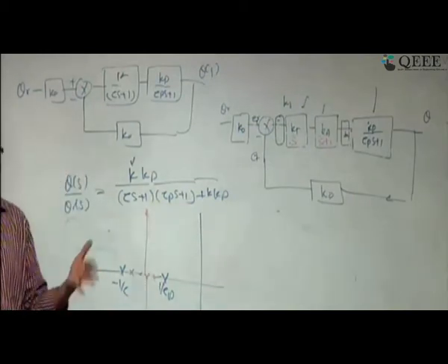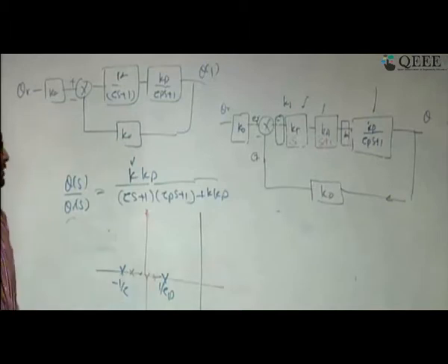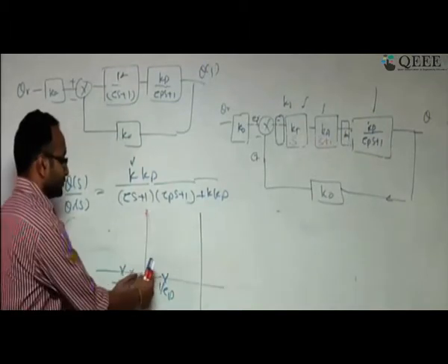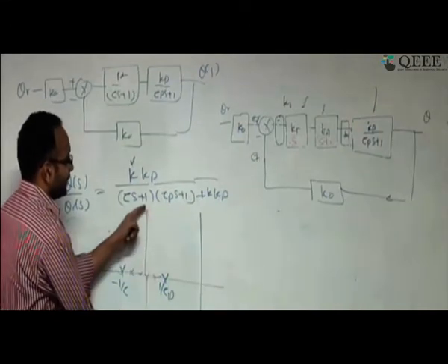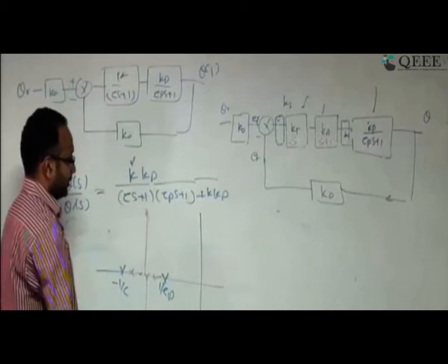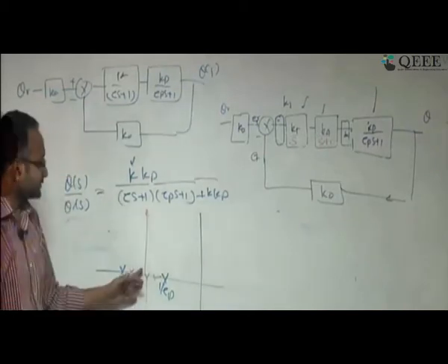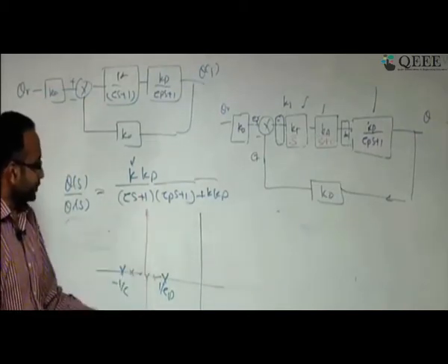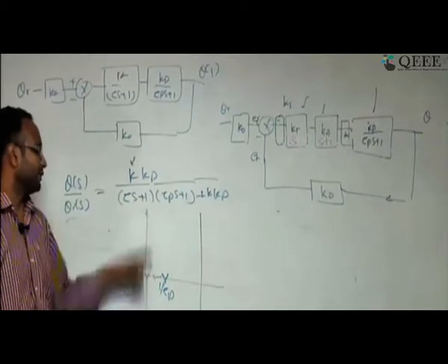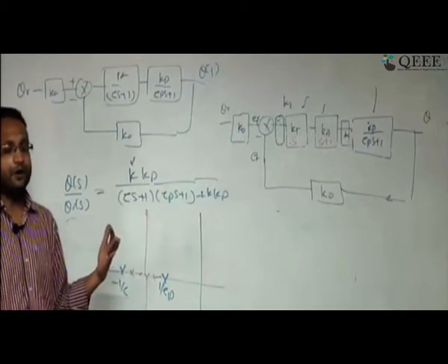You can check it by using different values of k. What happened? K equal to 0, 0.1, 2, 3. So this location of pole will come and will depart. It will become an imaginary component. Okay. This is, sorry, a conjugate location. So you can see here this part is coming, and once it becomes a conjugate, it means the system is going to have oscillatory behavior. That all of you know, that is the conjugate location. The system response is going to be oscillatory.